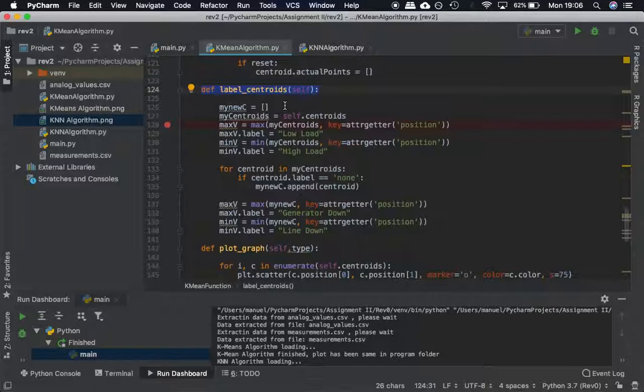For the last label, which means the line out, it is known that when a line is out, the path that the current will follow to reach the load will be larger, leading to a higher voltage drop. As the path is larger, the total impedance of the path is also higher, so to know which cluster will be tagged as line out, it will also be required to calculate the voltage drop.